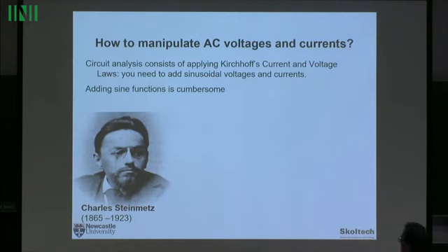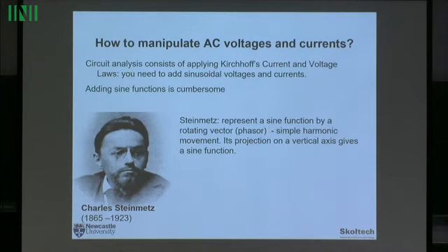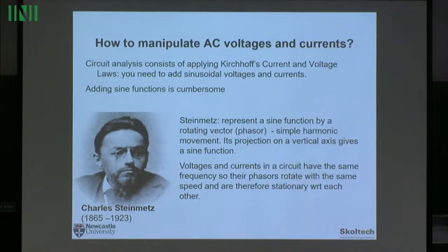So it's better to simplify it, and Charles Steinmetz came up with the brilliant idea to represent a sine function as a rotating vector, a phasor. Then the projection of the tip of the vector on the vertical axis will be a sine function.